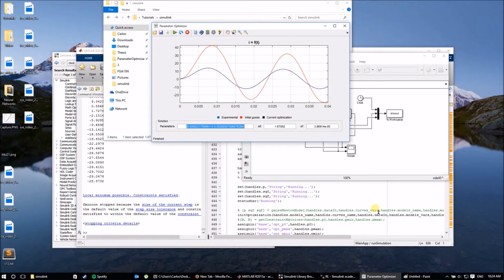This way I managed to estimate the machine parameters of a PMSM with less than 1% error. So it's something that definitely works and is the way to go. A more general approach would be to modify the simulation engine in such a way that you have these two states, like you would have an update method and a late update method, maybe like you do in game development. But that's another problem that takes a lot of time to do, and basically you have to modify it like this. That's my tips.